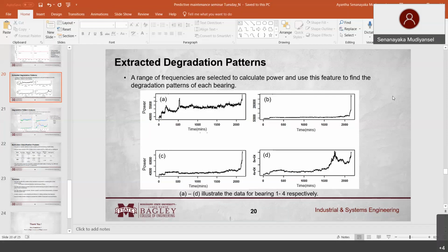Yeah, I get that they're individual, but how are you labeling them as fault or not fault? It's predetermined. For example, when we use a good bearing or baseline bearing, we capture the signal and label it as baseline and good bearing. Then we set different types of fault environments, start the machine, capture the data, and label it as faulty. We label the different types of fault classes, based on the faulty bearing.